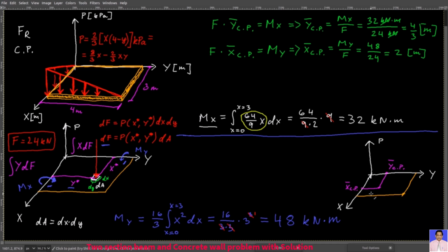They cross here, so your resultant force acts through this point, because this point here is the center of pressure of this load distribution. For as long as we have our rigid body assumption, this one and this one are equivalent to each other.